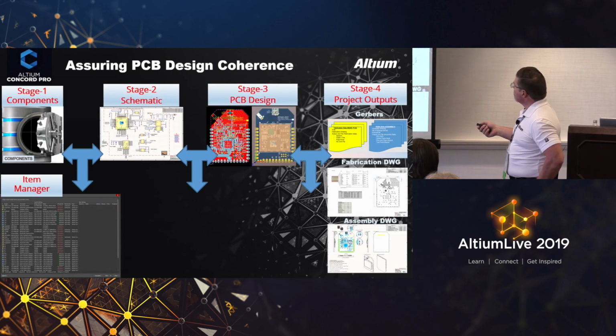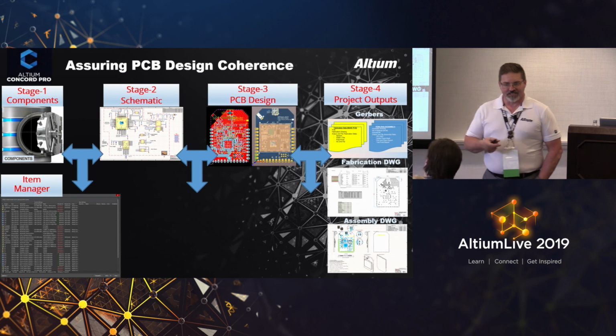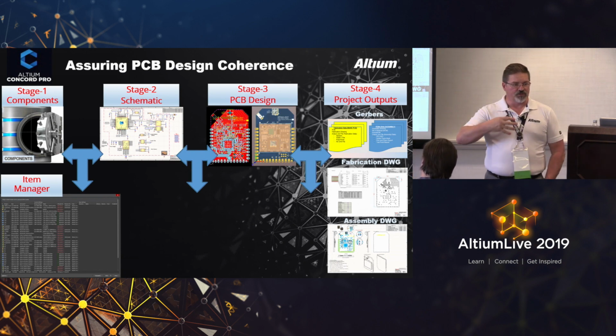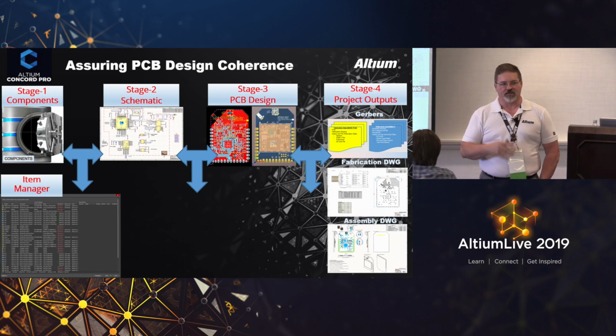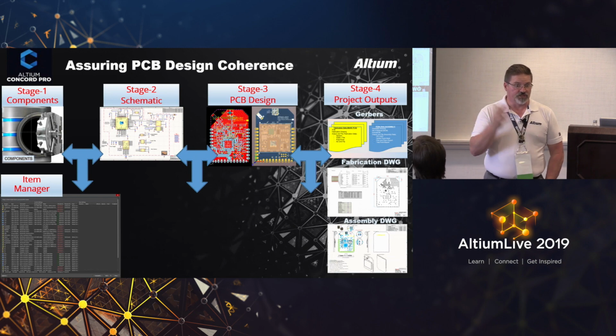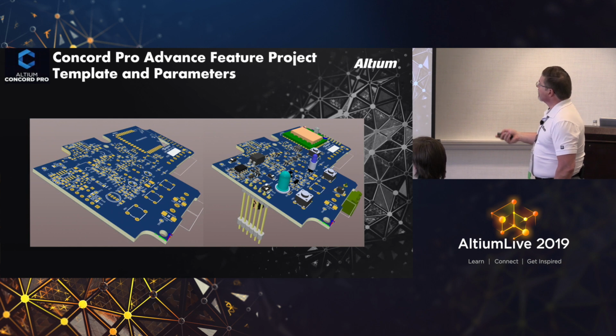There's also the syncing that happens. That is done through the syncing, pushing your schematic into your PCB. Whenever you do that, that should come back and say, okay, no changes. No changes, no differences between schematic and PCB. Then also the syncing of that.